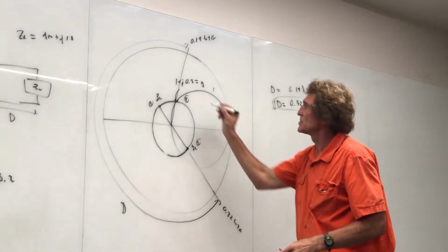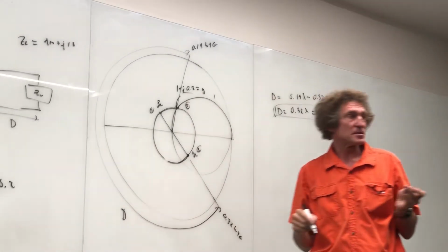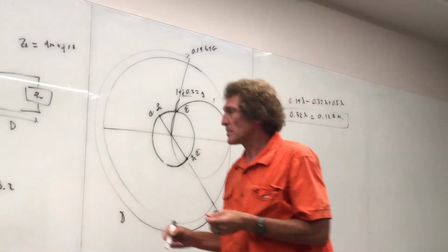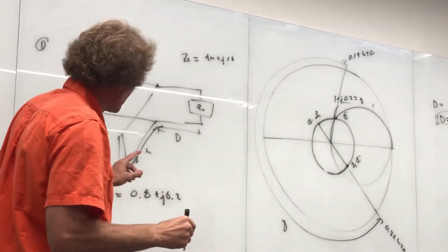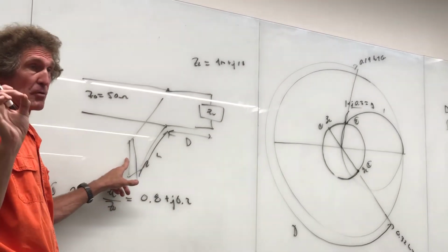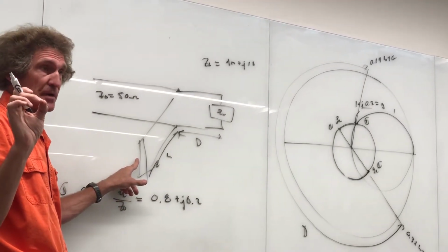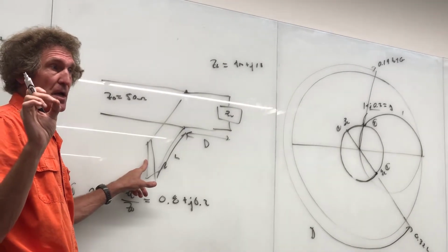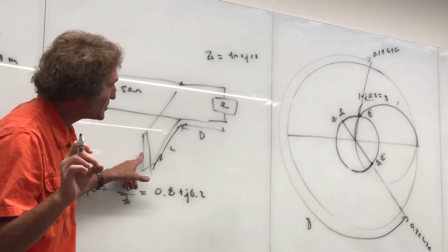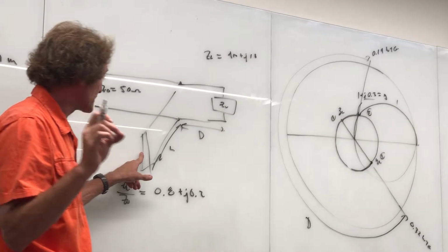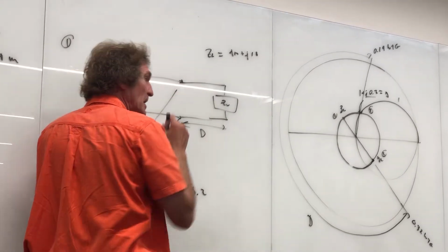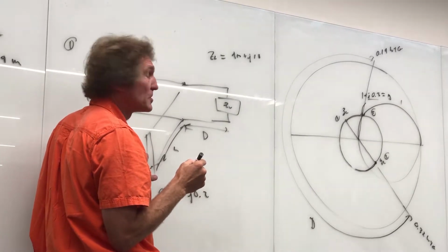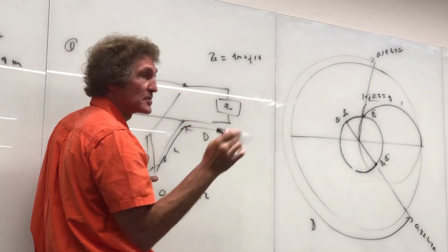Now, I have J 0.3 here, which is positive, right? So again, with this stub tuning, since this is a shorted stub, the impedance of the load is 0. The admittance would be infinite, correct, class? Right? And we want to make sure that right here, this stub has a value of minus J 0.3 in the admittance domain, correct, class?